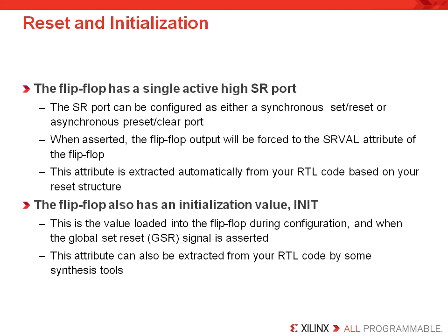You should recall that the 7 series has a single active high set reset port. That flip-flop with that set reset port can be configured as either a synchronous set or reset or an asynchronous preset or clear port, and that is defined purely by your HDL style. When asserted, the flip-flop output will be forced to that set reset value attribute of the flip-flop, which is inferred from your HDL. This attribute is extracted automatically based on the structure you use. So following good coding techniques for set reset is important to infer that value appropriately.